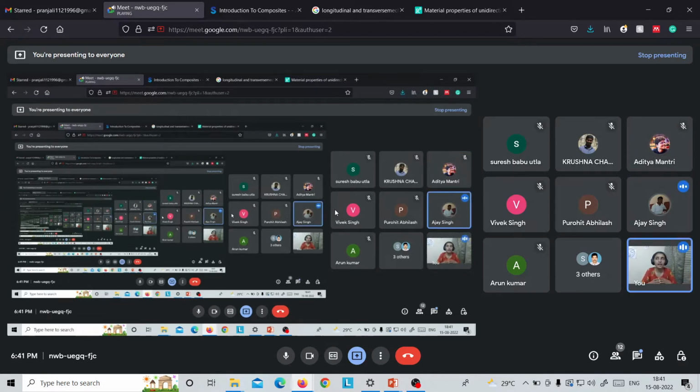Okay. So see, for all kinds of polymers, we define a lot of temperatures. The most commonly used ones are glass transition temperature and melting temperature. Then we also have crystallization temperature and degradation temperature. But all these are not typically explained by sir. They are not much used when we talk about mechanical strength. When dealing with polymers for designing for mechanical applications, only glass transition temperature and melting temperature are the two temperatures at which the properties tend to change.